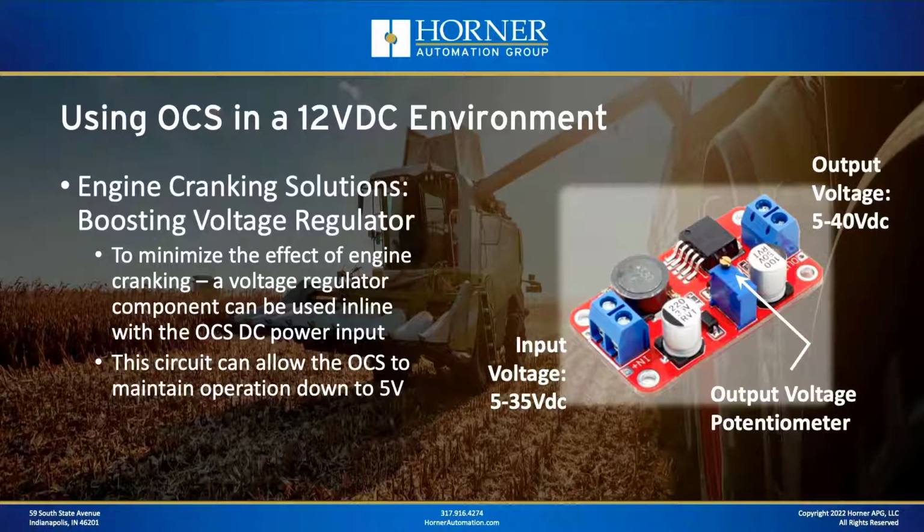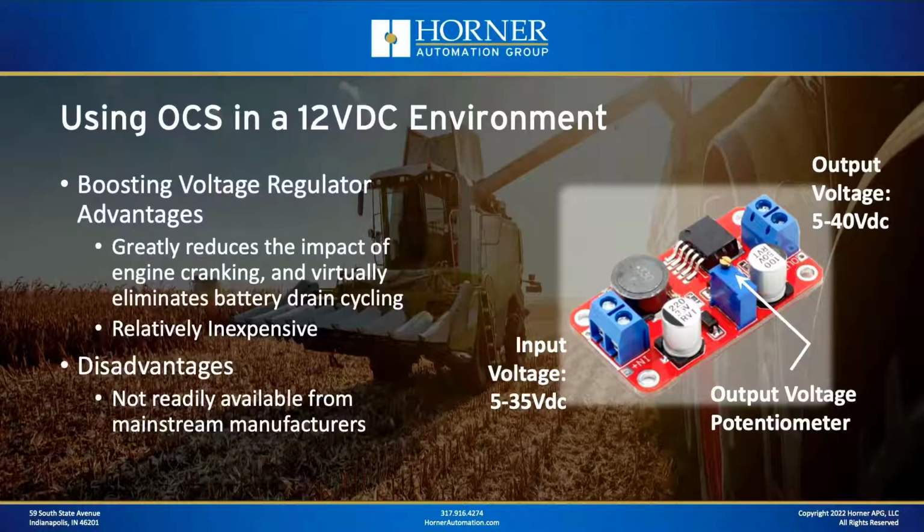Now it doesn't go all the way down to like 2.8 or 3 volts, which is kind of the lower limit of what you'd like to be able to support to never have a reset, but it will get you all the way down to 5 volts. Now what are the advantages here? Well, as you can expect, it's greatly going to reduce the impact of engine cranking, although it's not going to completely eliminate it when your voltage drops below 5. And again, it also has the benefit for helping with the cycling issue we talked about before. It can also help address that as well.